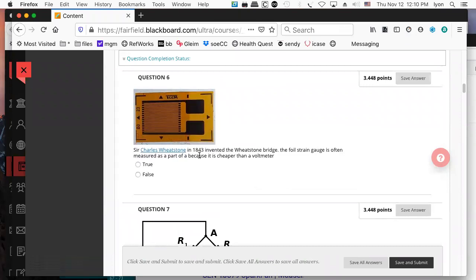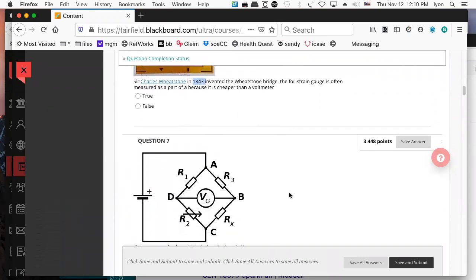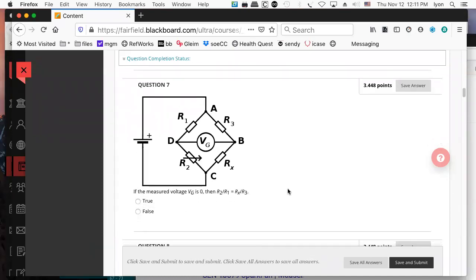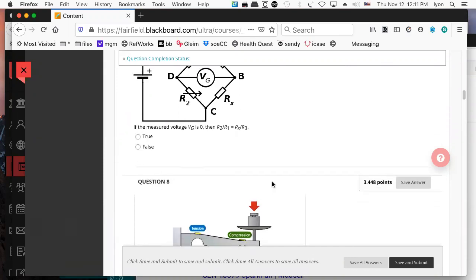So here's electronics from the 1800s, the Wheatstone Bridge, which we still use to this day. What we're doing there is taking one thing that's variable and two other things that are fixed and well known, and we're looking to see if there's a small change in resistance. This can be done without a computer, with a simple galvanometer. If you want to put a computer in there, you can certainly do that, and you can solve for one of the unknown resistances, R sub X. That allows us to essentially measure very tiny changes in resistance.